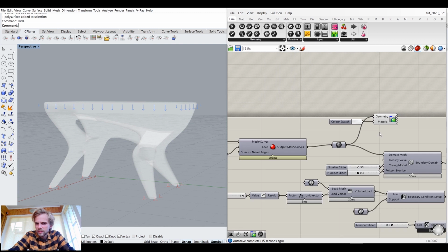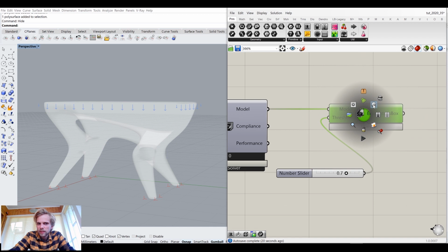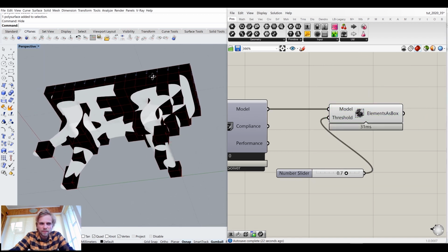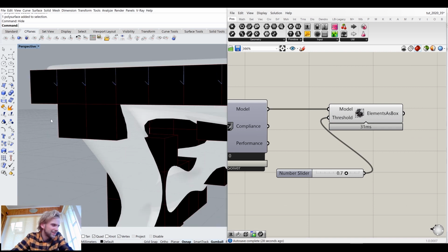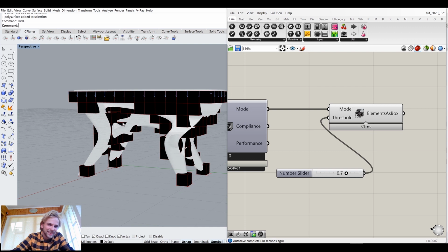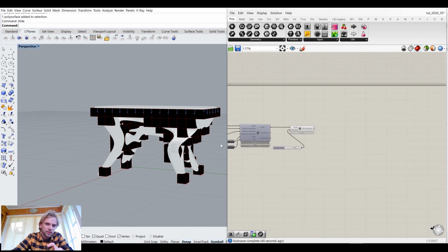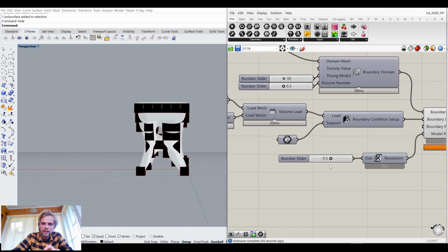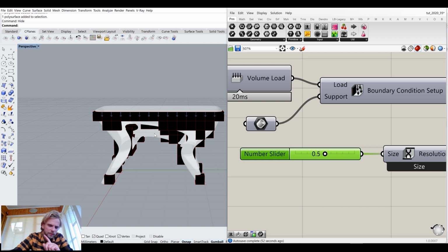Just something like that. That should be good enough. And this is my voxels right here. So right now it's not optimized, and these voxels are way too big, as you can probably tell by now. So one way would be for me to change the size of the voxel quite easily by going back here, and where I have my resolution, just changing the size here. But instead what I'm going to do is I will keep it true to scale.